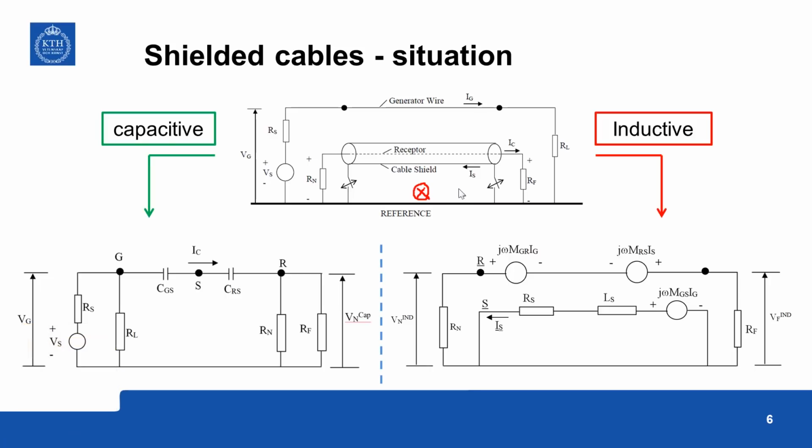So that flux is coming out of the paper. So you will have a flux coming out of the paper like that only if the direction of the current is in this way, from here to here. So the polarity is like this. So this will drive a current to oppose the original flux.